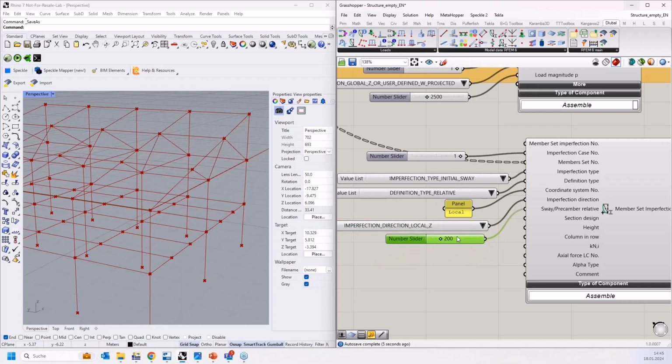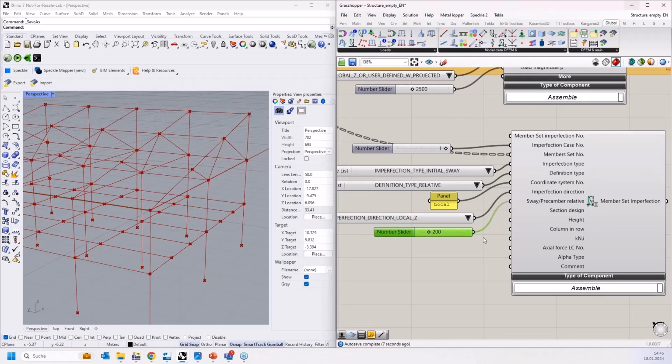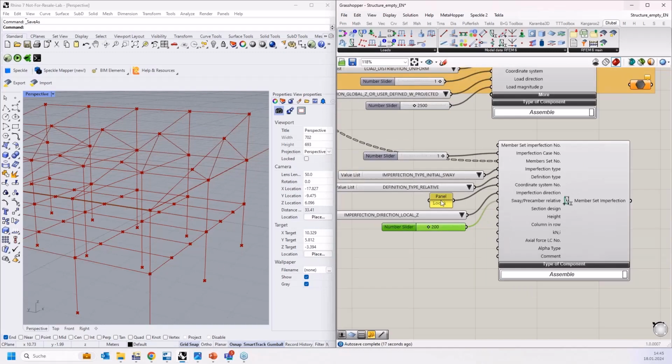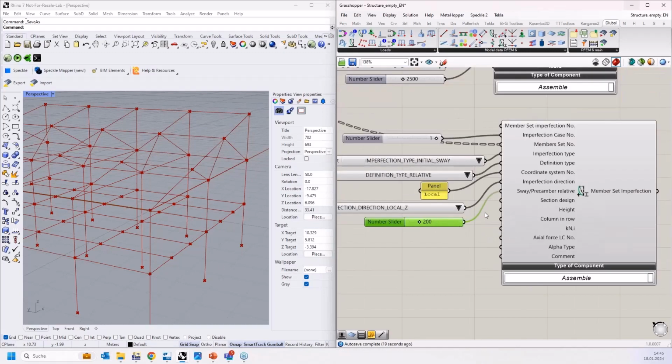You could optimize the sway. There are some, let's say, little bit more advanced formulas. If you consider the height of the columns and the amount of columns in one row, you can also, let's say, calculate a smaller value or a smaller sway. We have the inputs for that. I'm just not using it here in the webinar today, but that's also possible.